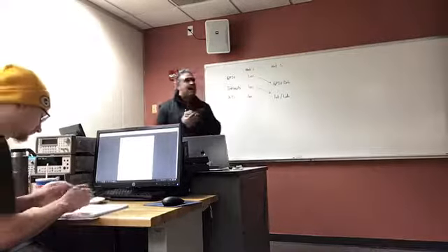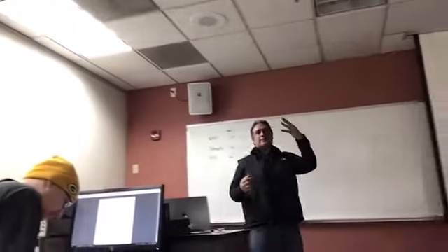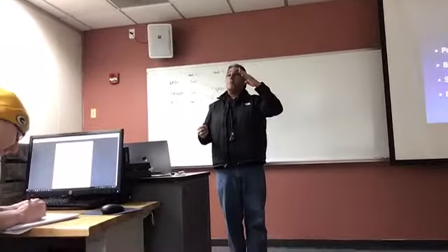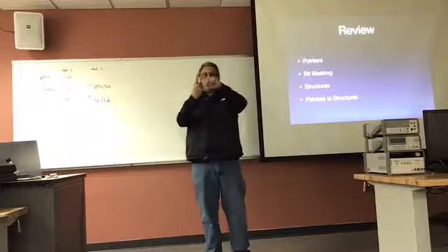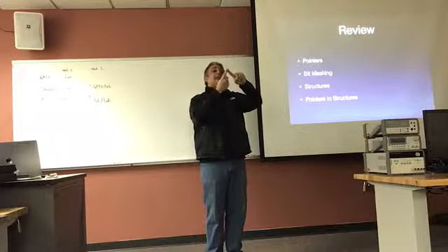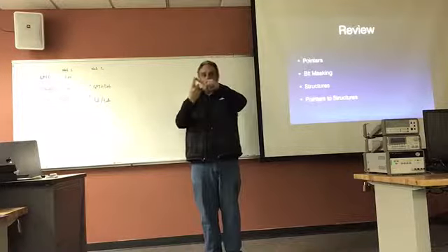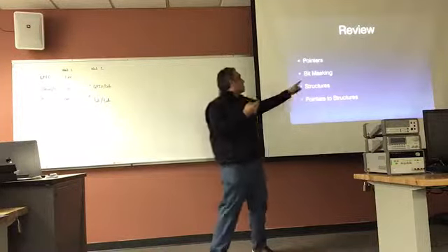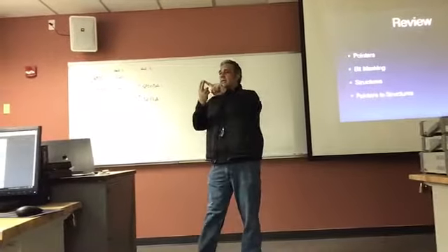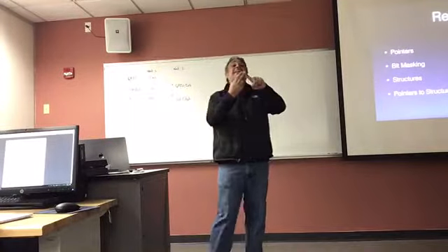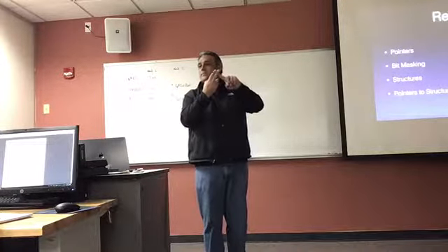Okay, the review is going to have 4 areas, okay? Which are the 4 areas that are the most important for us, especially here where we're doing microcontrollers, all right? The idea of pointers, right? The idea of pointers is what gives us access to the hardware. So that's why we're going to be doing pointers, okay? The second one is the concept of bit masking. And the idea of bit masking is the idea of gaining access to single pins inside of the processor.